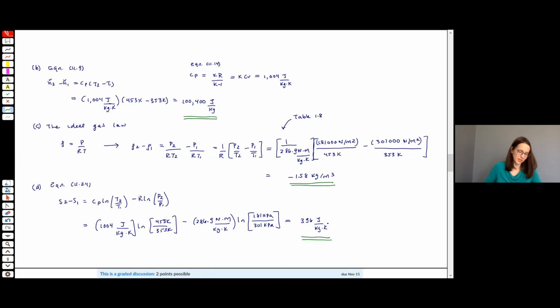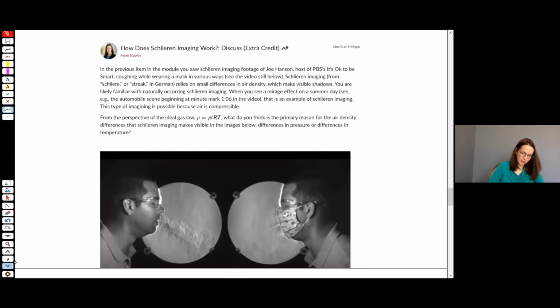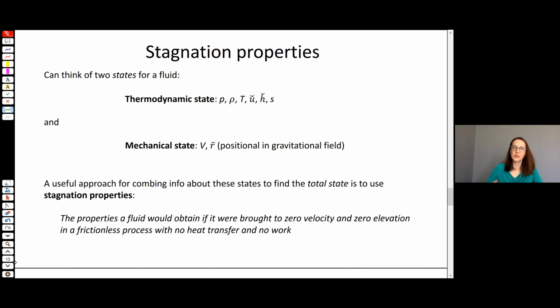All right, in the interest of time, we're going to skip the optional discussion about how you could calculate the loss, because it's beyond the scope of this class. I've got a little more I want to cover, but does anyone have a question about this example? I think it's pretty straightforward to calculate these problems. You must always remember to put both the pressure and the temperature in their absolute form, and not use the static pressure and static temperature.